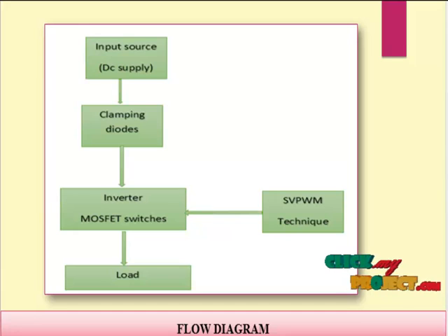Next we see about the flow of our product. In this proposed work we overcome the drawbacks of the existing system and compare the result with the existing method. In this proposed work, a 3 phase 6 switch full bridge inverter is used to reduce the harmonic level. The space vector pulse width modulation technique is very helpful in making the switching pulses with better output performance.